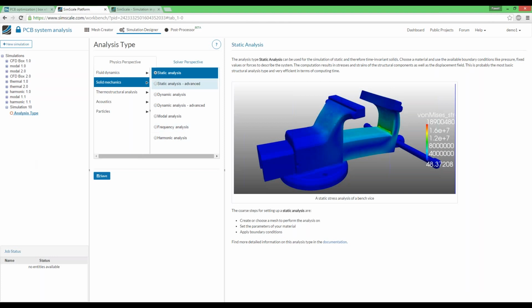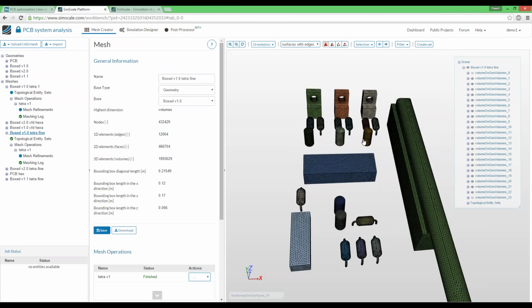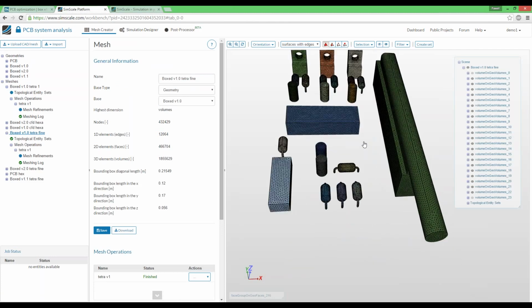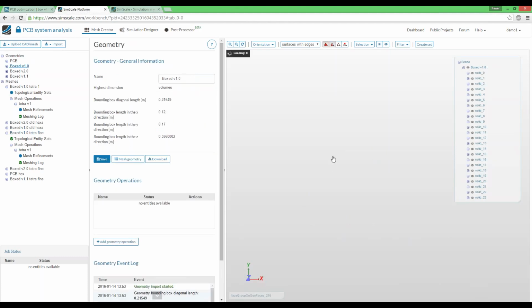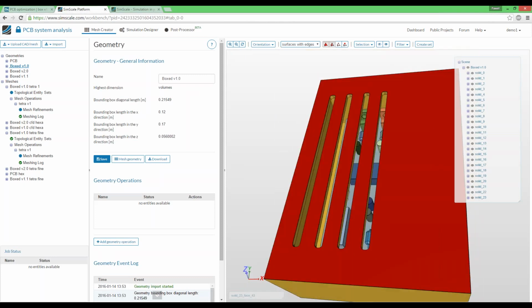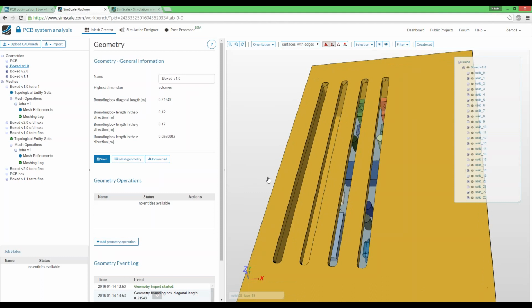All right, there's a clarification of the question that we had. Is the option available to generate the mid-surface from the solid? After that, the mesh is generated from the surface. In general, what is happening within the mesher itself is that we will have the mesh created first on the surface itself, or first on the edges of our geometry. Every edge that is present over here will be split with certain fineness, and later we'll start creating surface meshes and surface discretization of the geometry.